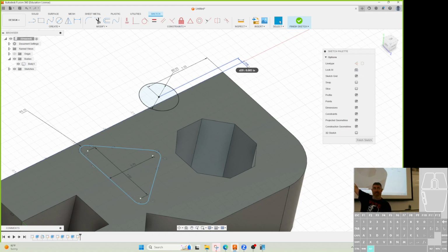If you use the hole command for this, am I going to be mad? No. Actually, there's a lot of times that I will use the hole command for this. One of the sample problems for the CSWA has a big circular cutout of the side of a part that's got a couple different depths on it. And for that, I use counterbore holes, because I can create two concentric things at the same time with one command. That's easier, even though they're not holes. And so it's using the command to best suit what you want to do.